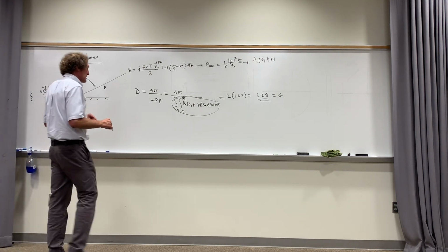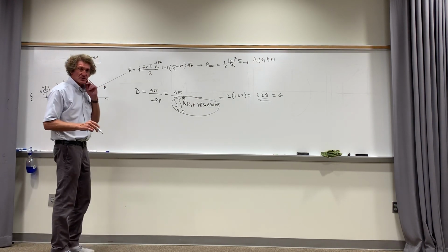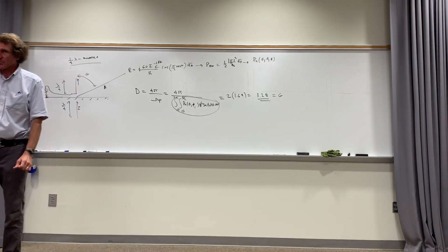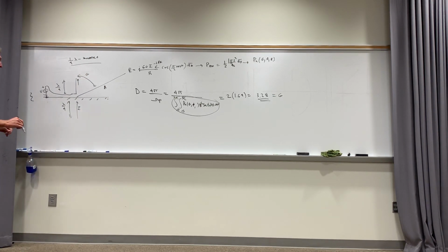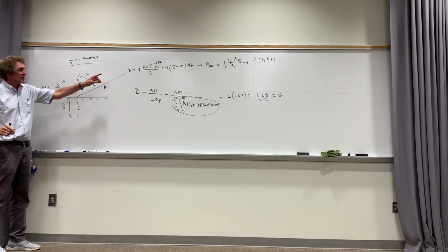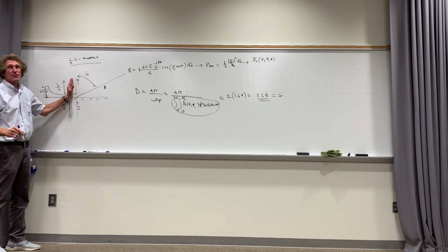But there is one thing that is different, and that's the radiation resistance. Now, I'm going to make this argument with you. Listen to me, I don't have to go through an integration. Y'all agree that if the same electric field occurs out here that would occur for a half-wave dipole for a given current I, right?